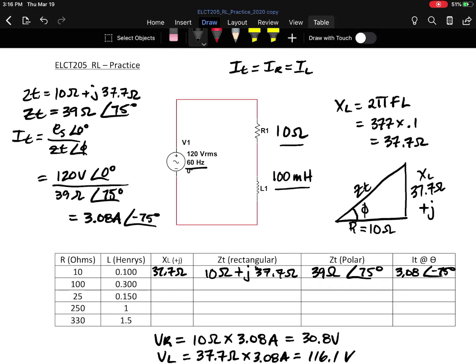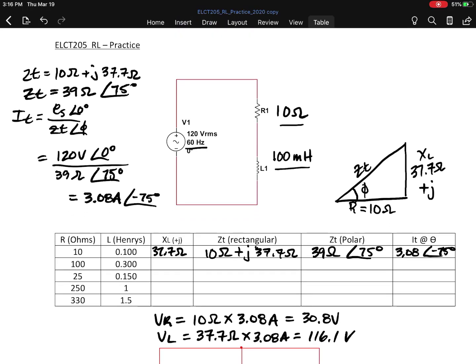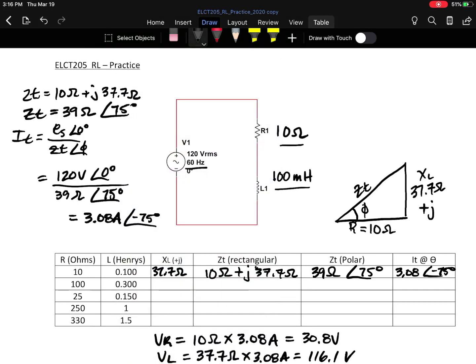So just going back here, what I'm going to do is demonstrate Kirchhoff's voltage law using a voltage triangle. Just above this impedance triangle, I'll show the voltage triangle. Now, when it comes to the voltage triangle, realize that you're really going to have a triangle that looks exactly the same as the impedance triangle, because of course every quantity is multiplied by I total to give you the result.